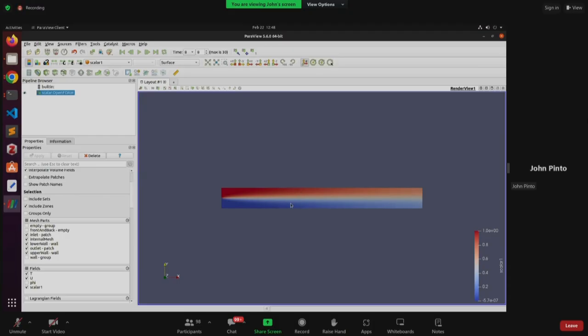So if my diffusion were high, it will even mix. It is mixing along the length. You see the concentration going down. Okay, and whatever was here, it is diffusing to the bottommost region. You can try playing around with this by changing the diffusivity values and see how the diffusivity value affects the results. So this is my second case.